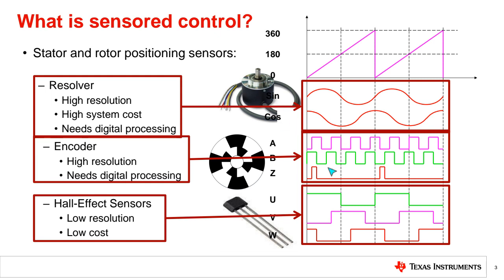Maybe I said to you, Hall effect sensor has three legs. Here you see U, V, W. One of them VCC. VCC means voltage supply. One of them ground. Another one signal, 1 and 0 signal. We have three legs.